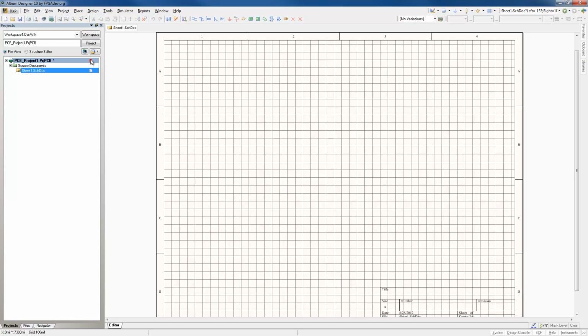So the first thing you'll notice is that there's nothing over here where my cursor is. Normally, if you have Subversion up and running and this project is in Subversion, you will see little bubbles over here. We don't see that because even though we do have Subversion running and Altium can make contact with it, we have not told Altium to commit this to any type of Subversion repository.